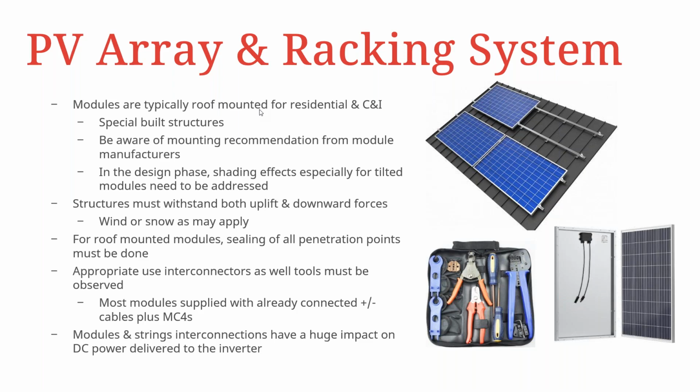All structures must be able to withstand both uplift and downward forces. For example, wind and snow in Europe, or areas where snow does occur, and then obviously high wind areas, for the uplift of modules. For roof mounted modules, sealing of all penetration points must be done to ensure that no water leakage can occur, and appropriate use of interconnectors as well as tools must be observed.